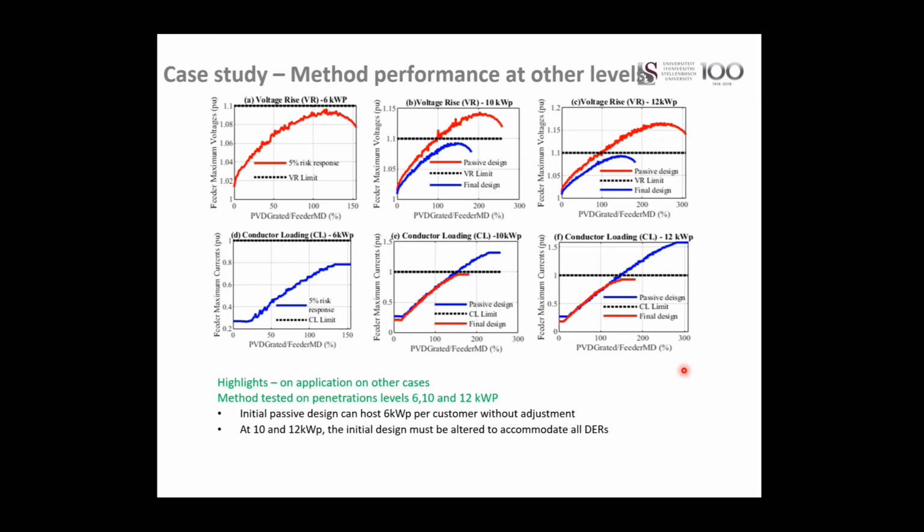So now coming back to exactly what Marcus you are saying. Thanks, Mondi. I think you touched on an aspect that I wasn't implying. There are two sides to that. If you've got a DER system, you've got regulation inside the point of common coupling, and also backwards to the point of common coupling, and they might be different. So your constraints with the household appliances and so on are being regulated, but then there's also the thing backwards into the network and supporting network voltage.